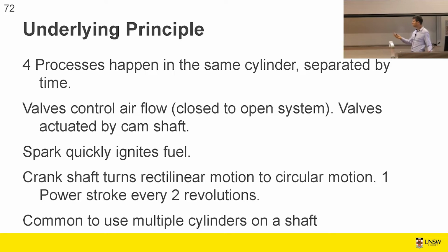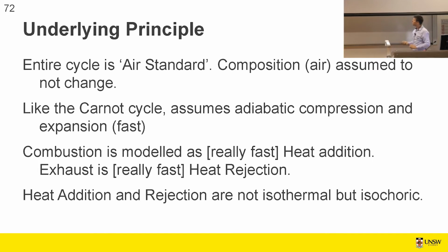And it's common to use multiple cylinders on a shaft. This is something you're familiar with. 4-cylinder engine, 6-cylinder engine. And the idea there is, while one cylinder is firing with power, the other cylinders are exhausting or compressing. So you've got maybe 4 cylinders doing their 4 different processes, 1, then 1, then 1, then 1. Actually 1, then 3, then 2, then 4.